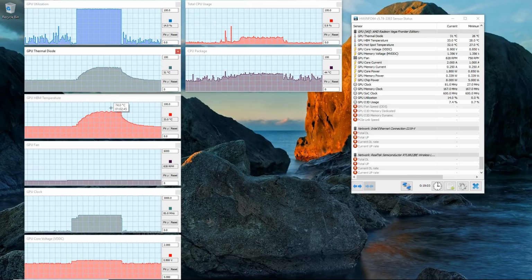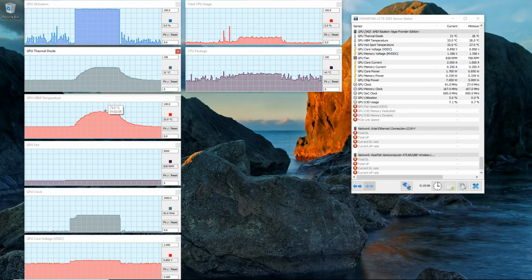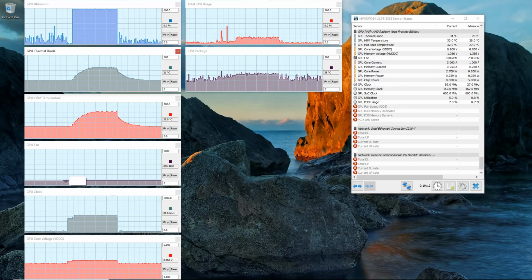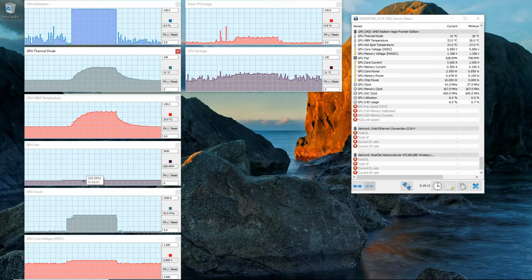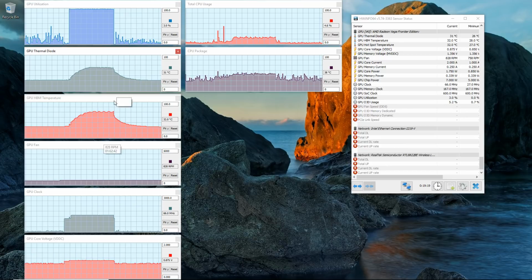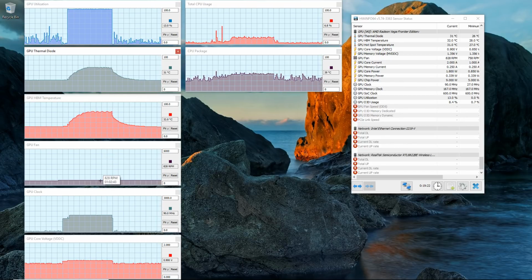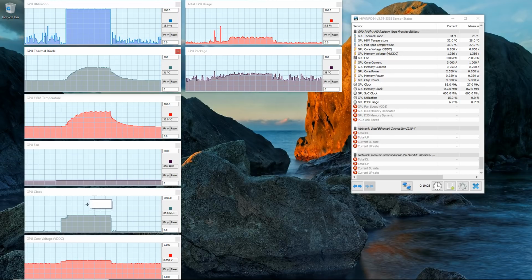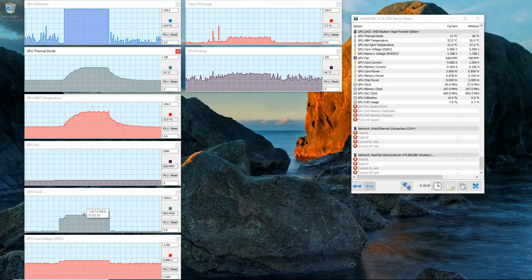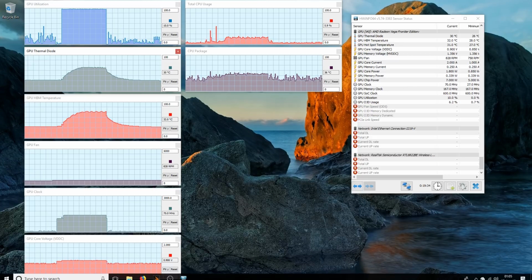for the thermal GPU. The HBM, like I said, runs a little bit warmer. It shows up as 74, 75 degrees here, which is acceptable in my case. You'll see that the fan didn't really get up that high. It was only running at 827 RPM, and I received these temperatures at 827 RPM, or 828. So the card has plenty of room to work from this point. And you see the clock here. It hit about 1400 that we had specified.